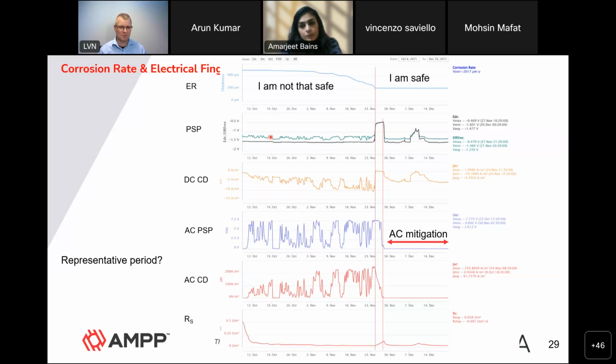If you lose an ER probe, well, you need to bury another one. And that's the price that you have paid for becoming aware of that problem that you have. But in most cases, and the operators of our ER probes have come to an understanding that if the ER probe is telling you a warning, I have corrosion, they need to go through the electrical fingerprints to find out why and make corrections so that the probe is no longer corroding, and therefore the pipeline is no longer corroding or in risk of corrosion.